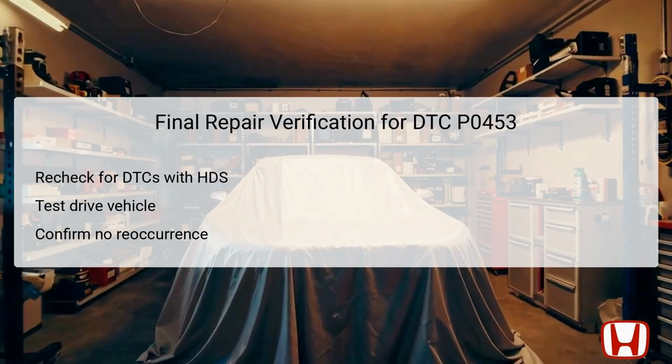After completing all necessary repairs and replacements, it's crucial to conduct a final verification. Begin by rechecking for any DTCs with the HDS to ensure that DTC P0453 has been cleared from the system and no new codes have emerged.